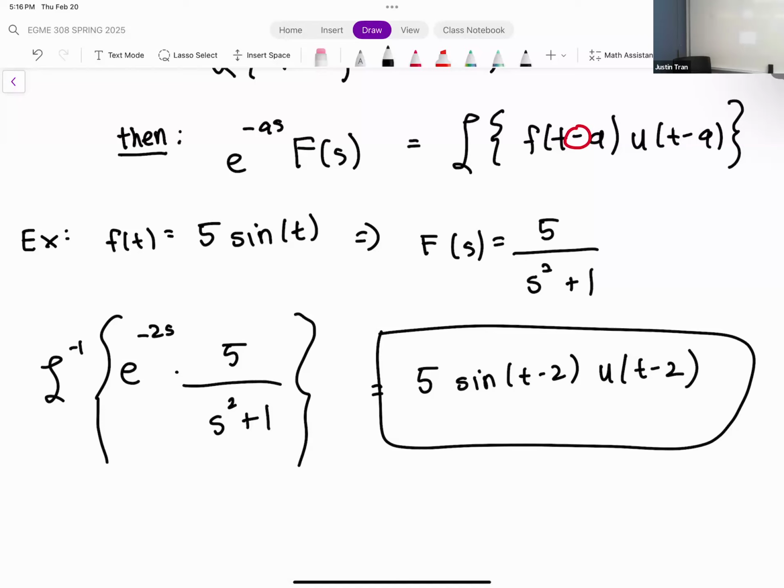The thing I would change is the overall stiffness of the system. You can change that, like any kind of oils or springs that they use to tune the system. We use constant force springs to help fight gravity. So you might want to make those a little bit looser, because then it'll loosen the damping, so it might oscillate a little bit, but then it might help reduce that, or you can try strengthening it. One or the other.